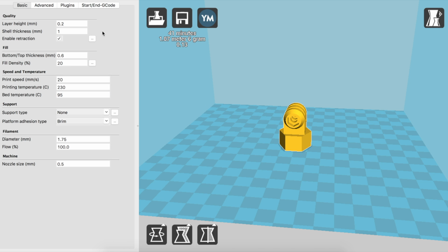If you want to tinker with your printer even more, you might be able to get finer details with a thinner nozzle, etc. But for now, you're probably going to switch between 0.1 and 0.2 millimeters, depending on the printer that you have and the nozzle size. Some people might even go to 0.3 with different materials and different nozzles, etc.